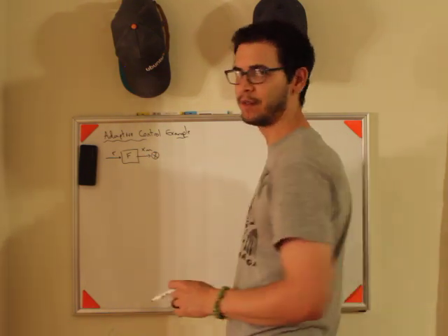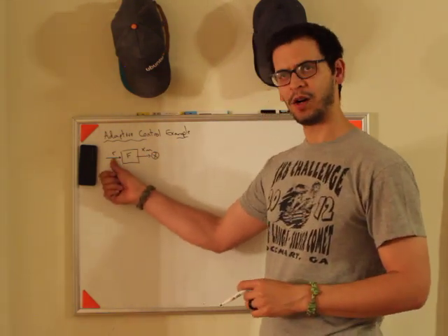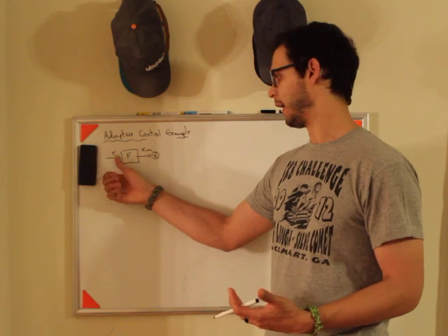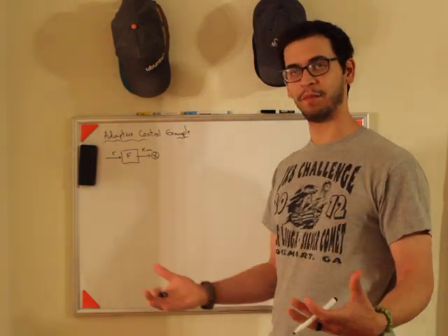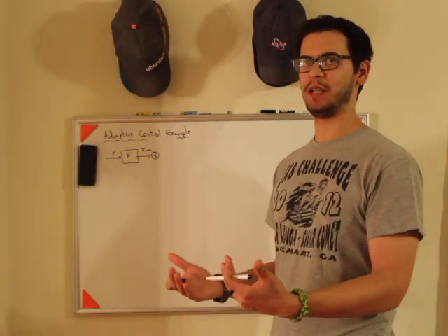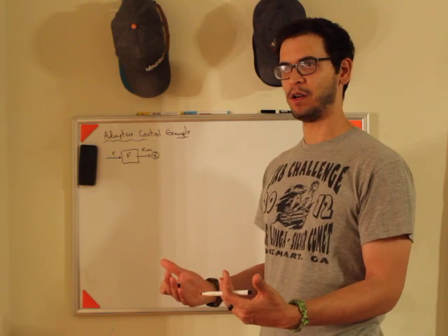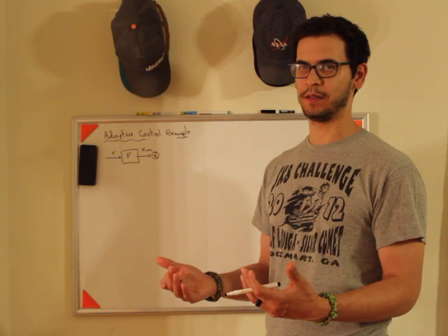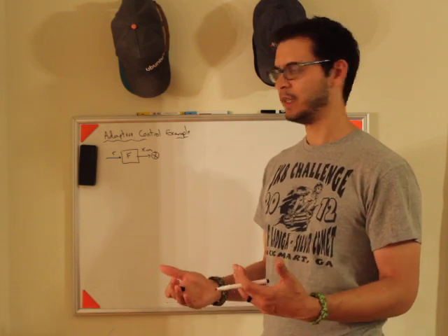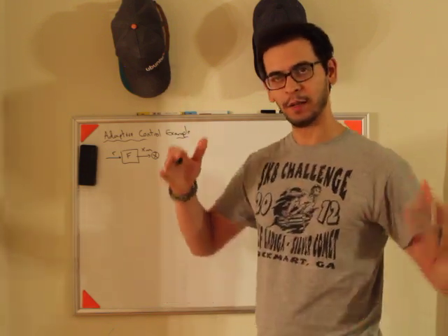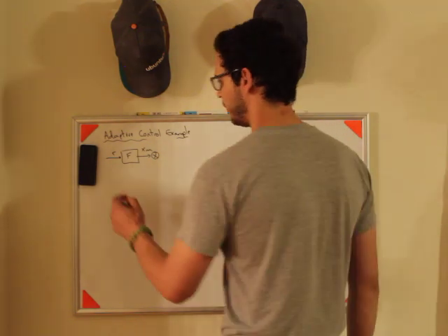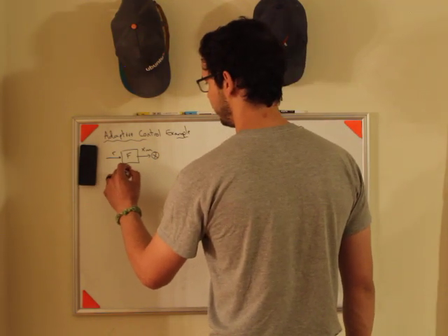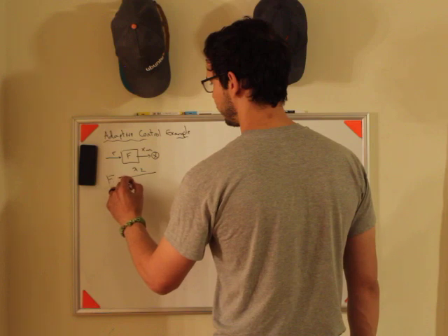The reason why we have this, by the way, is let's say R is a step input and your system has a lot of mass. A step change command is going to be a very harsh transition. It's going to cause accelerometers to go crazy, and it's going to cause a lot of noise in your sensors. So a lot of times it's nice to bring that up slowly. The easiest thing to make F here is just a simple second order transfer function.